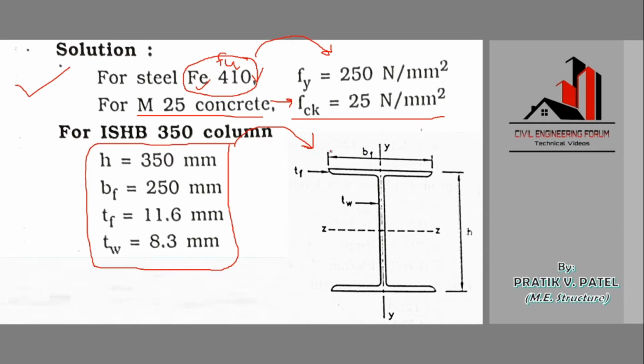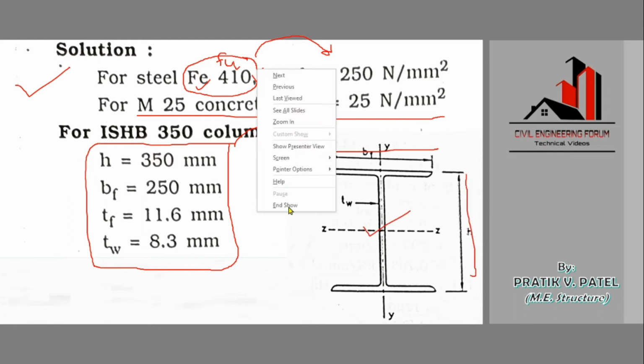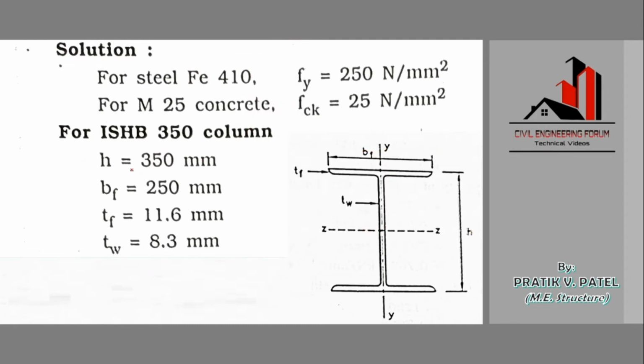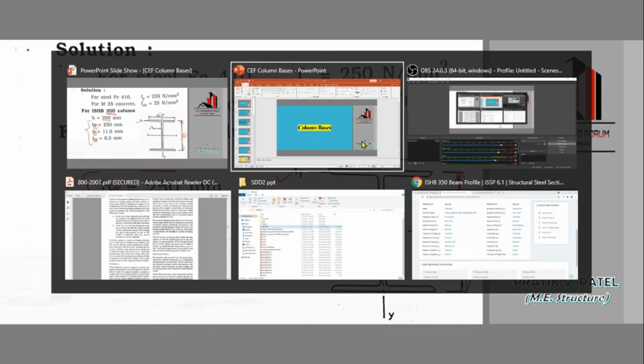That is, this top is known as flange, this is known as web, this is the web. Now the height is 350, given in the grade of the section itself. This 350 indicates the height, or we can even say depth, but here we would indicate it by height. This is H 350. Rest of the criteria, that is BF, TF and TW, that is width of the flange, thickness of the flange, thickness of the web, all these things are given here, and the details are given in steel table. Let me just show you.